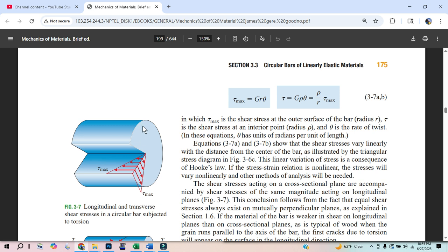Now this is also similar to when we pull on something axially. If I have a square bar and I'm pulling tension on one side and the other, I can take a slice of that bar, or even just a cross-sectional cut. If I'm putting a force on this end, on that cross-section there's that same force. And I can take any cut along that whole bar, and I'm going to get a force on that cross-section.